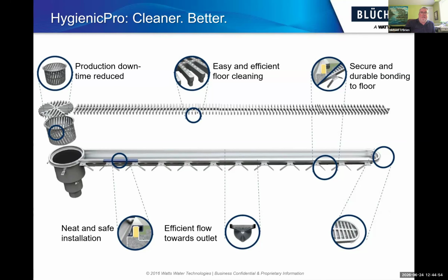So in practice, typically the water that was used to get those solids and that waste into the trench drain is enough to carry it all the way down the channel and into the basket, and therefore out of danger.